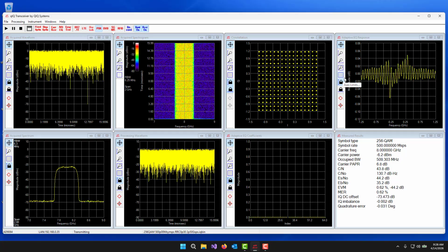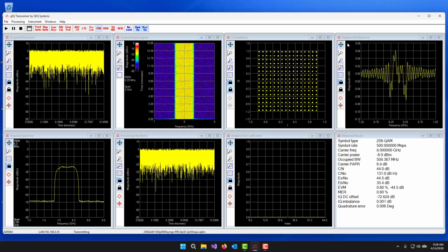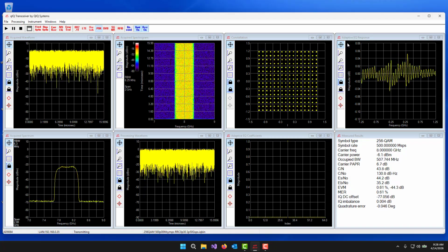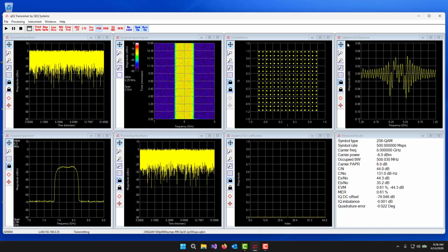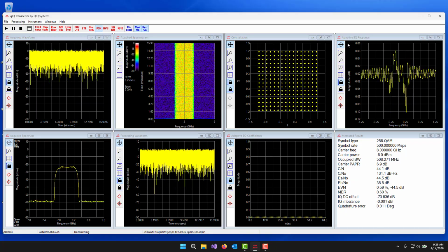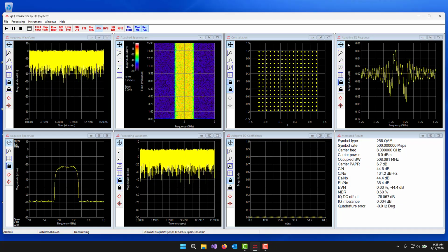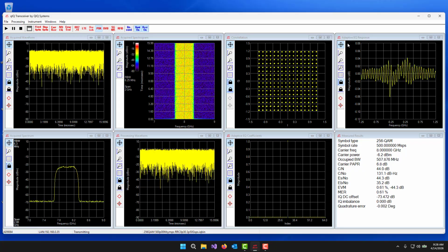So we are now doing two levels of calibration and equalization. One is using those fixed coefficients that came from the chirp, and then we're doing adaptive equalization on top of that, because we know what kind of signal we're using, and we can do a better job because it's a PSK QAM kind of waveform.